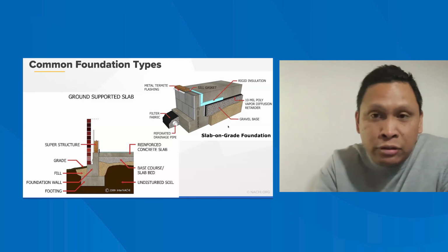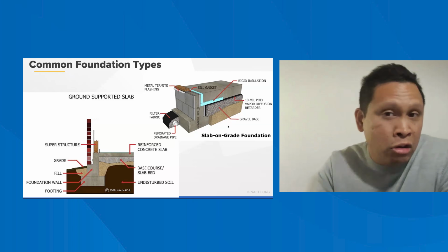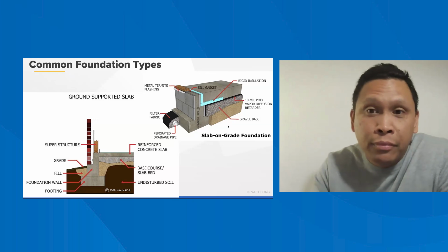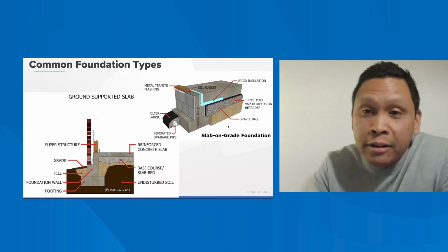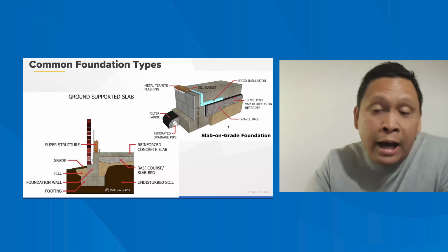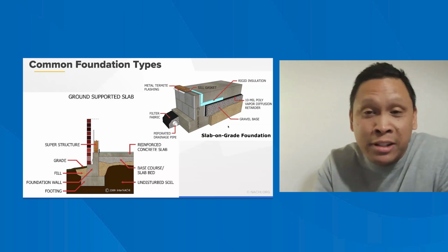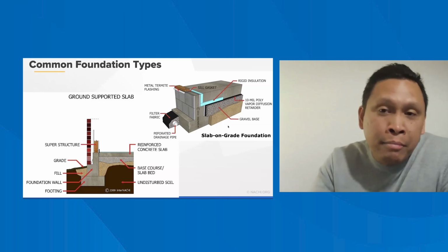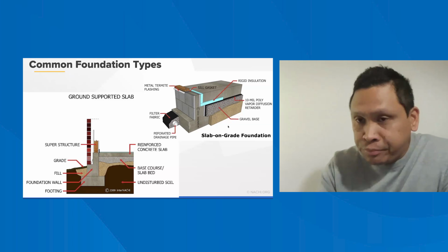One of the things that you'll find, if you're in the garage, let's say, and you just kneel down or look underneath the wall, sometimes you may actually come across a completely missing section of the sill gasket, and you can see straight to the outside. It happens. Sometimes you might see a whole section of the wall that is completely missing the gasket altogether. It happens. It's important to know that that gasket is there for a reason.